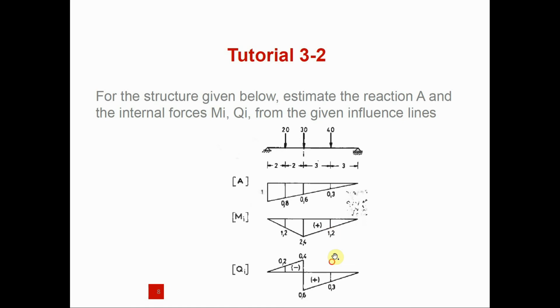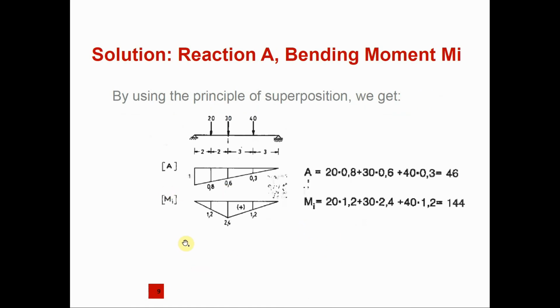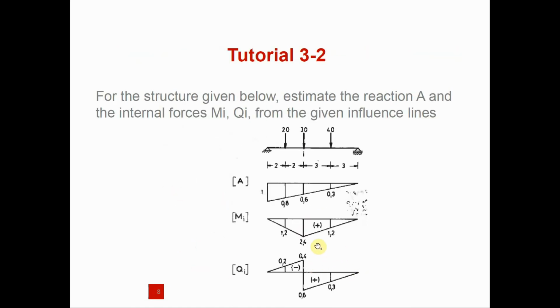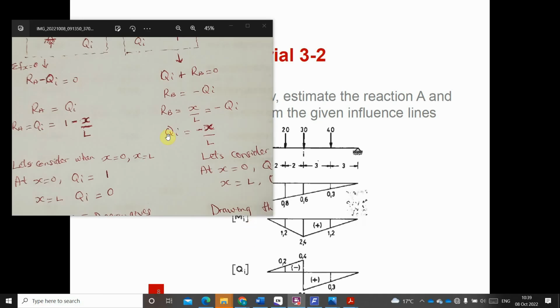Now let's go to the shear force diagram, if you can recall it from the other time. Let me quickly get that for us. For the shear force, we have this formula, 1 minus ξ over L, and likewise minus ξ over L. If you can recall, you were told that if we are considering this side of the shear force, you take into consideration the member B, and if you are considering this side, you take into consideration the member A. Why are we doing that?